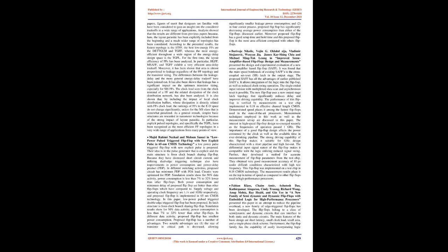Majid Rahimi Nezad and Mohsen Sainai, in "Low-Power Pulse-Triggered Flip-Flop with New Explicit Pulse in 65nm CMOS Technology," propose a low-power pulse-triggered flip-flop with a new explicit pulse. Their idea is in the pulse generator, which is explicit, and the main structure is from the clock branch sharing flip-flop. Because they have decreased short-circuit current and utilize a dual-edge triggering technique, they also have improvements in power consumption and power delay product (PDP). In different switching activities, the proposed circuit has minimum PDP with FO4 load. Circuits were optimized for PDP.